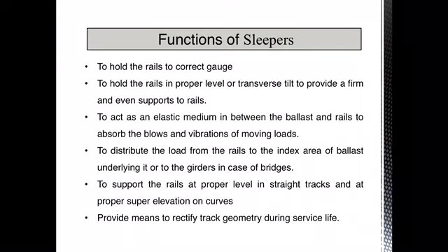The sleepers also act as an elastic medium between the ballast and the rail, so as to absorb the blows and the vibration of moving loads. What are the moving loads? Moving loads are because of the trains. Usually the trains travel at very high speed, so while the train is moving, certain vibrations and impact blows will be caused. So the sleepers you have provided must act as an elastic medium to absorb those vibrating loads.